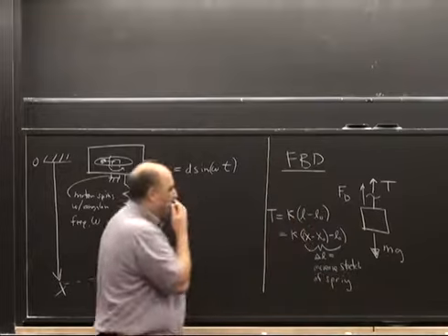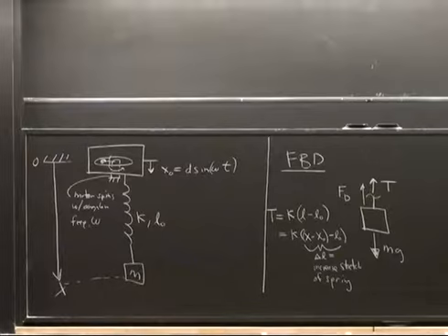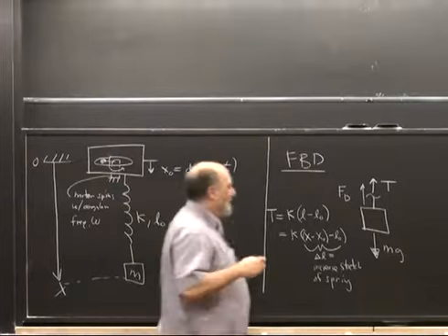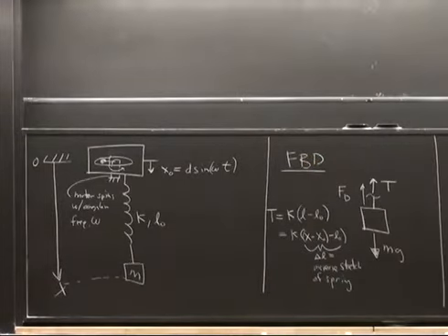So it's easy to make sign errors if you don't set this up carefully. What I recommend is from this point in your life forward, or maybe from a week forward, all things are in tension. Tension is positive, stretch is positive. If something is in compression, you call that a negative tension. It's much easier to do problems that way than it is to try to psych out when it's in compression, when it's in tension.